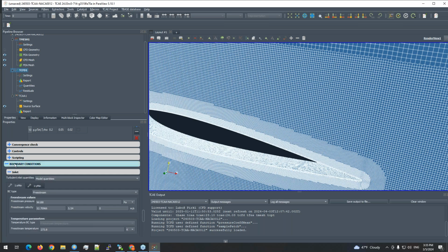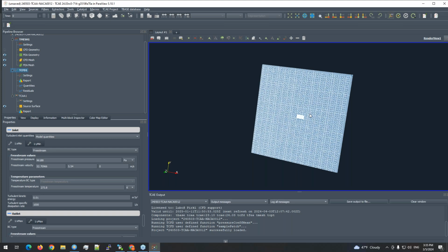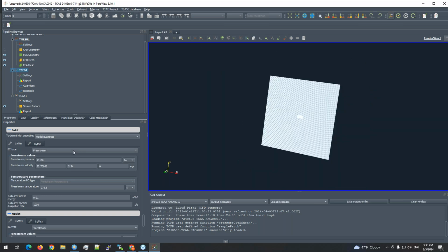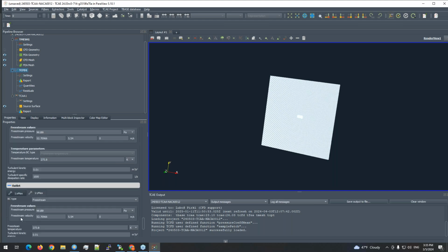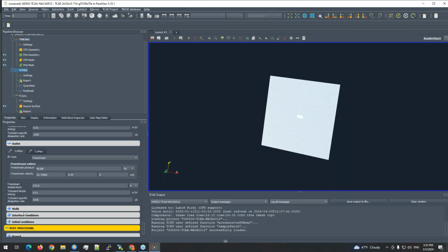All right, so here I think it's all, only the inlet and outlet boundary conditions, because we have a domain which is simple to create. For this reason we have basically two inlets, from the X min and Y min in this case, because we are simulating a positive angle of attack. So we set free stream velocities and we set the value of the free stream pressure and the inlet velocity vector, and basically this is set for all the inlet and outlet boundaries.